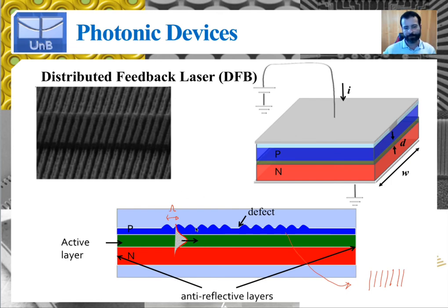The fact that you have this corrugated structure here will have the same effect as the multi-layer stack film, because you can imagine that when this transverse mode is on this region here, because you have more of a large refractive index material on this cross section, the effective index is going to be a little bit greater than when the mode is right at the valley, right? So here, if this refractive index is smaller, the effective index will be a little bit smaller than it is right at this position.